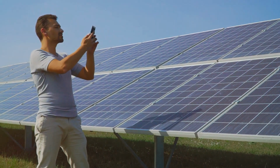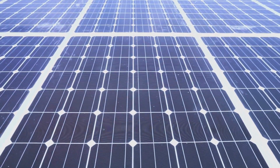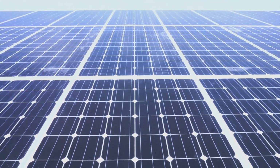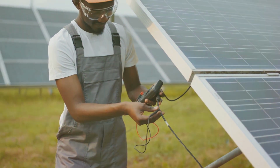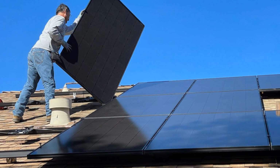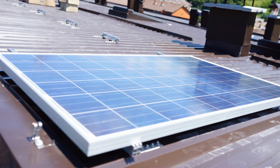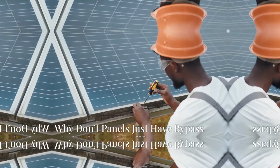Another shading solution comes from panel design itself. Panels with half-cut cells or shingled cells split the solar cells into smaller sections, increasing the number of paths for electricity to flow. If one section is shaded, it doesn't impact the entire panel as much. Panels like LG Neon R and Canadian Solar Haiku use these configurations to reduce shading losses and can often be found in complete solar kits.